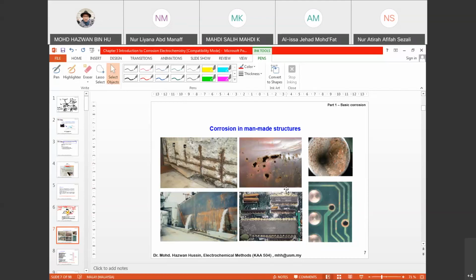Yeah, that's corrosion. Basically, if you notice inside your remote control, you will have a circuit board like this. This is actually where the button will be functioned. So most of the spoiled remote controls normally means that you will have corrosion that happens on the contact. Okay, probably you might wonder, how does this corrosion happen? Maybe when you press the remote control, your hand or the remote is quite wet.